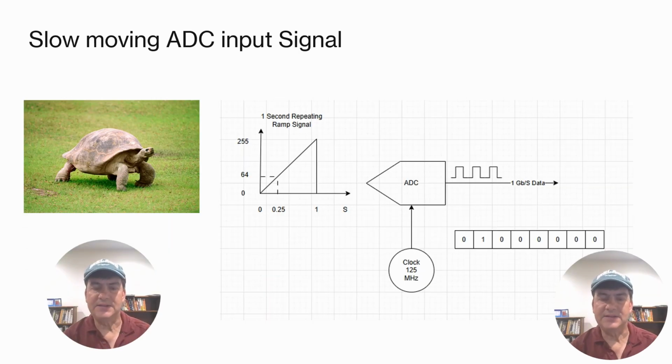What is bit slipping? So what exactly is bit slipping? Bit slipping is a method of aligning to the correct word boundary by barrel shifting the captured bits until the parallel output matches the expected value. When I first learned about bit slipping, I didn't think it could possibly work for an ADC serial stream. But then I had a eureka moment. For bit slipping to work, the analog input to the ADC must change slowly compared to the sample rate.